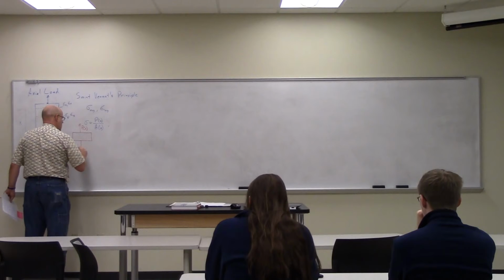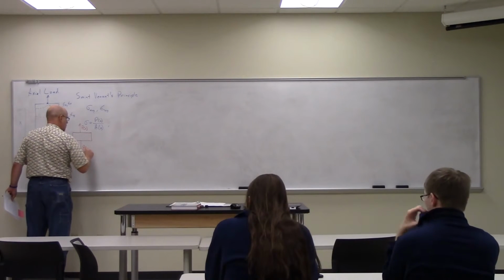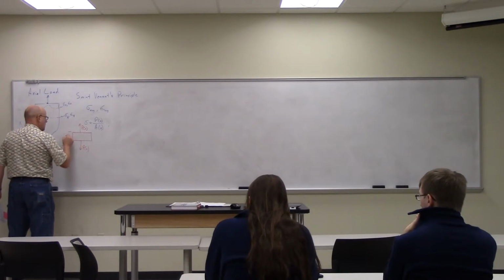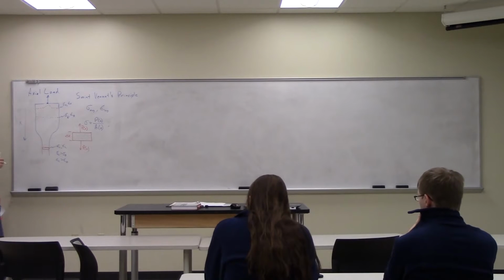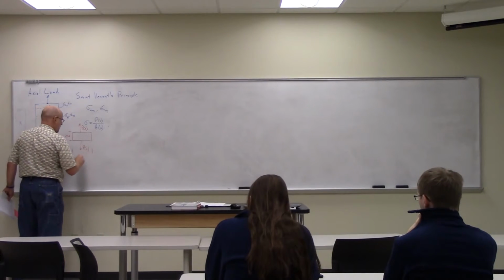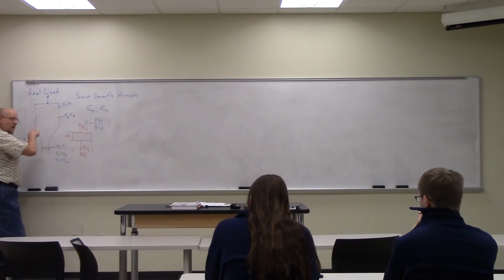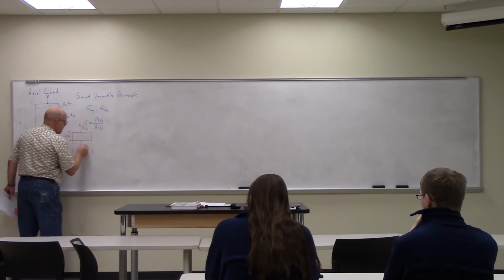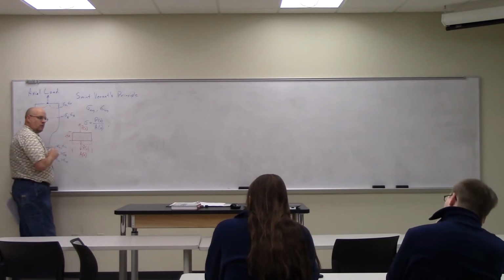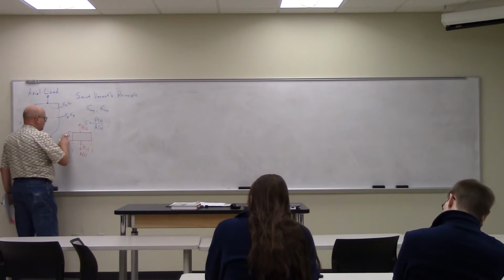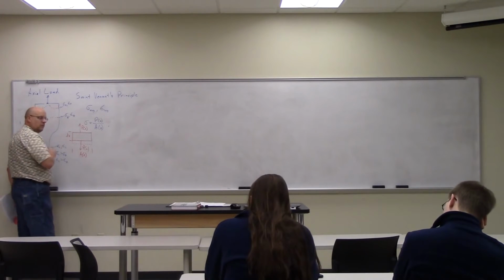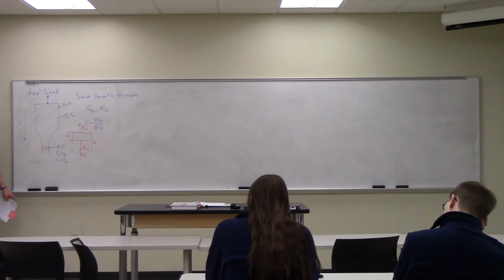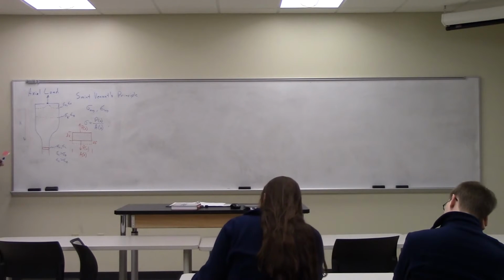So that little section is experiencing a load that depends on its position. That little section has a dimension delta x there. It has a cross-sectional area, A, that also depends on x. Right? And as I pull on it, it's going to stretch by an increment like this, right? So as I get this small enough, this becomes dx, and this becomes d delta. Remember, delta was the amount of stretch. Okay?